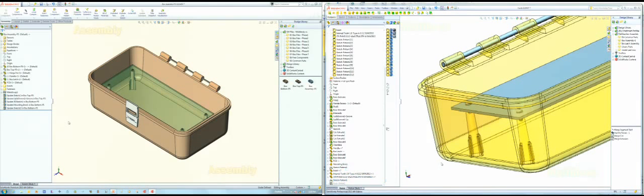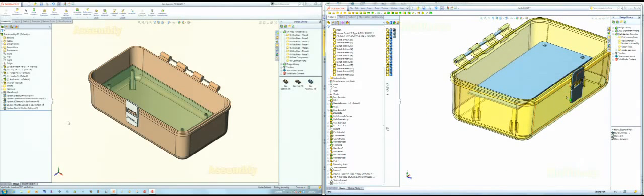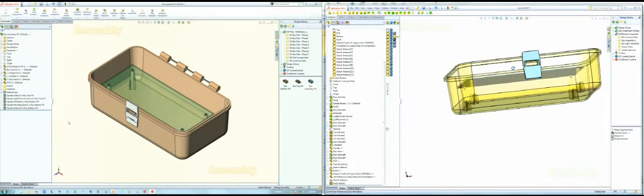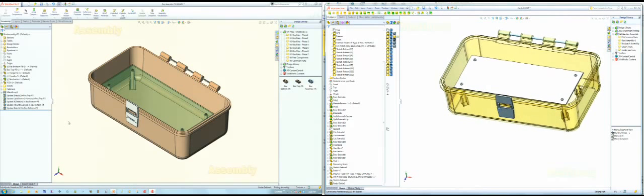So I'm going to make a pattern of that. When SolidWorks does a pattern of a body, it uses the move copy, and it gives you an extra set of screws and washers and all that. So I actually have to delete one so we get the right part count. All I did is take one set, the two that were overlapping, and get rid of them. You'll figure that out when you go to make a bill of materials of this. So that's how we had to get to that point. We've got all the components in it now to hold the circuit board in, and they're all tied to that sketched pattern on the printed circuit board. Does that make sense?